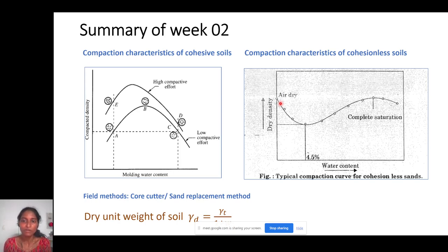This has already been discussed briefly in the video, so let me have more discussion on this. If I add a little moisture content to this dry soil or dry sand especially, what happens? In between two sand particles, if we have a small tube kind of opening, that creates a capillary action.